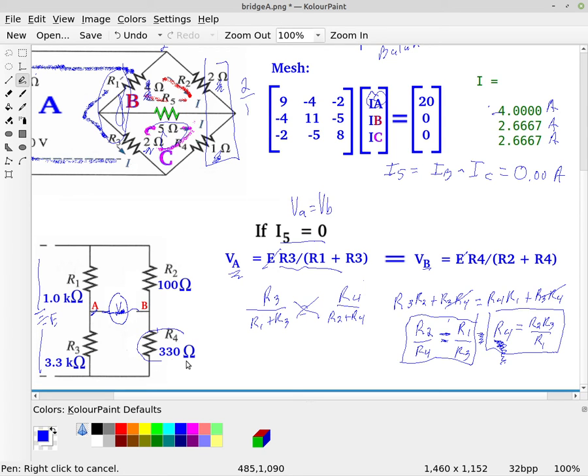And so we have here for R4 we put in what's called a strain gauge, which as you compress an object, that compresses the strain gauge, which is really just a fancy resistor that changes resistance as it's compressed or put under tension. And therefore we can then measure that change and determine how much force is being applied. So this is a very, very common circuit for sensors trying to measure various physical properties such as force or pressure or temperature.